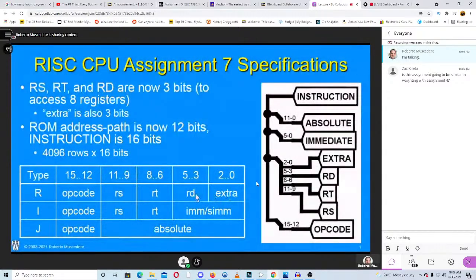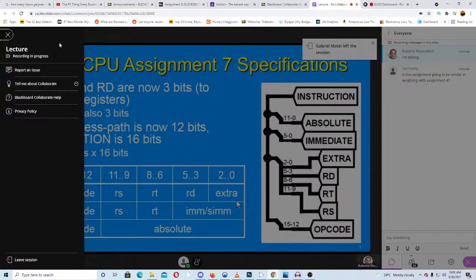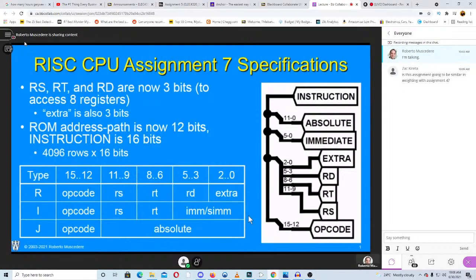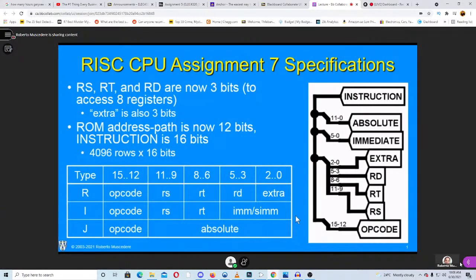Do over here if I only have 6 bits, right? So we're going to have to put in some sign extension hardware here to facilitate this. So whenever we use an immediate number, and as I mentioned before, when we use constants generally in code, they're not usually very large. They're usually relatively small. So we don't have to encode a full 12-bit number in here.